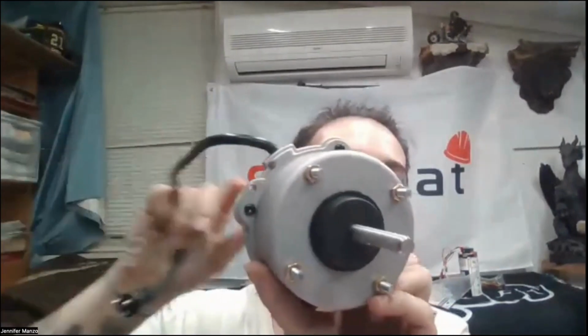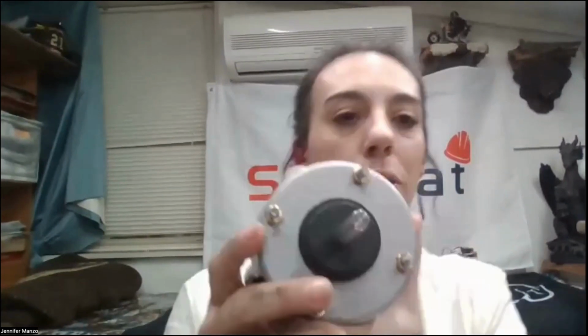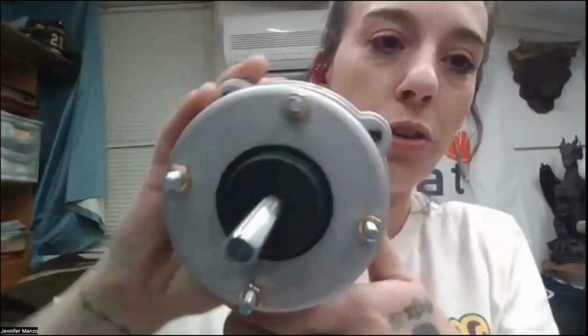Yeah. So this is a fan motor. It is not special. They scare people a lot. And a lot of people do what I used to do and don't amp them out because they're like, I'm not opening the front of this case, getting in there, and then amping that out. When you don't, you end up opening that case, getting in there and replacing it because these go bad all the time. They're super easy to replace. As you can see, a few screws, and that's it.